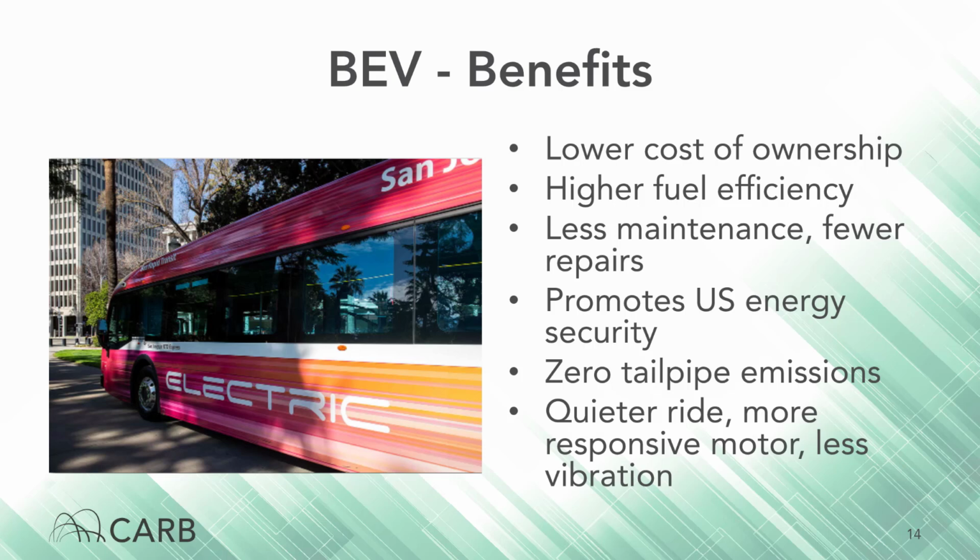Also, upfront prices are likely to decrease to match conventional vehicles as production volumes increase and battery technologies continue to improve. BEVs report higher fuel efficiency because electricity is fundamentally more efficient than conventional fuels. Additionally, frequent starting and stopping and elevation decline allows for BEVs to utilize regenerative braking systems. Regenerative braking is a technology available on most BEVs that captures the kinetic energy from braking and converts it back into electricity to be stored in the battery. In doing this, it also slows the vehicle, and many vehicles can be stopped entirely by using this feature.